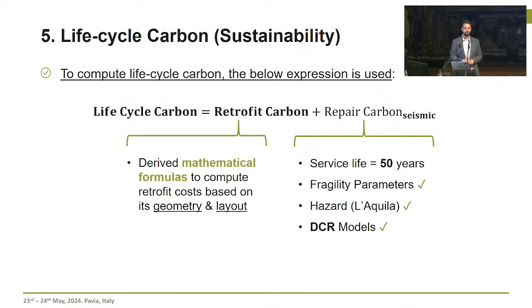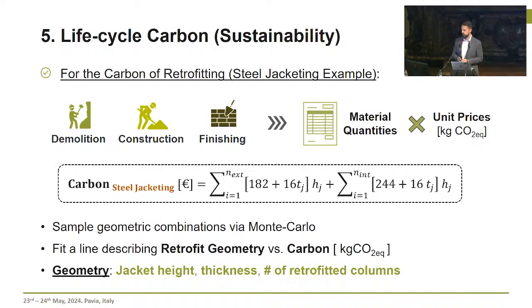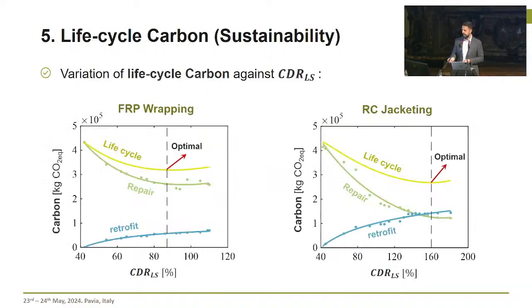Moving now to sustainability and life cycle carbon, it can be treated exactly like the cost. It's basically the carbon of retrofitting, sorry, plus the carbon of repairing seismic damage. It's exactly the same concept. Instead of euros, we have now carbon emissions. I also fitted equations that express the three strategies as a function of the retrofitting geometry.